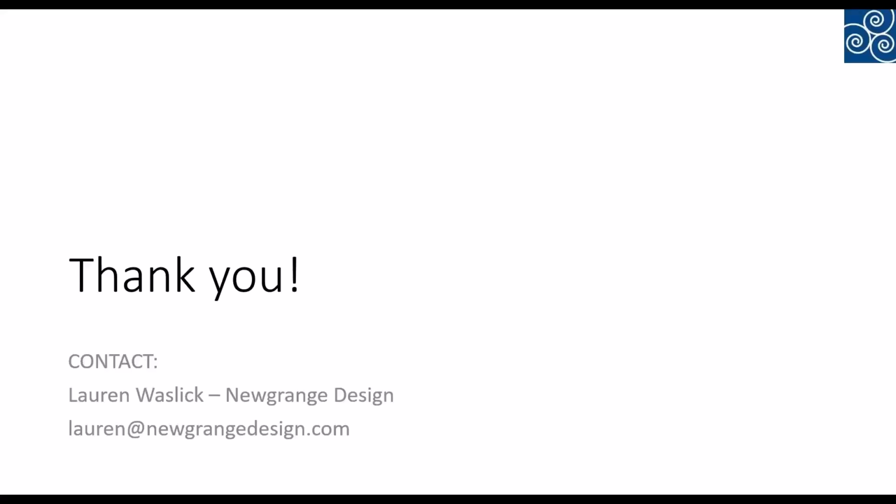Got it. Thank you. There were a couple of questions just around general, I think, Lauren, you went into kind of what are some of the consequences of using flex, but people asking what are the advantages of going with flex versus just using maybe multiple boards with connectors and cables? Yeah, so I saw that question there, and really the biggest benefit I've seen to flex is when you have a really size constrained area, like within a cell phone, you'll see a lot of flex designs because they're trying to make them as small as possible, because it allows you to remove those large connectors that can take up a lot of space and large cables that sometimes can be a little cumbersome. So that is a really nice benefit of flex, it allows you to really compact your design into a very small space. And it will also save a little bit of the cost and time that goes into assembly without needing to plug in as many cables or connectors that are required.